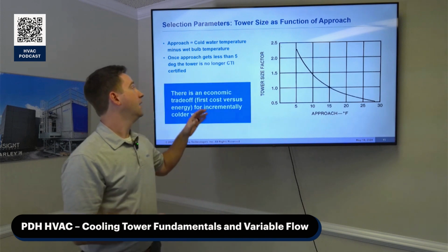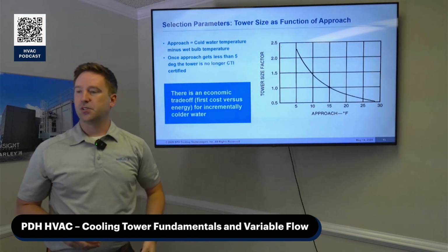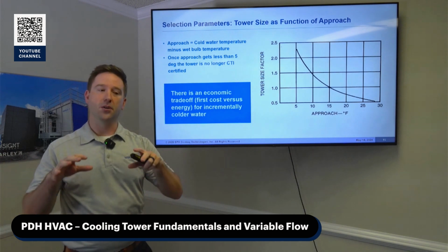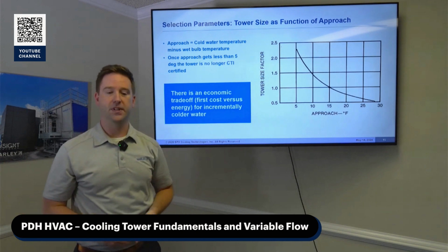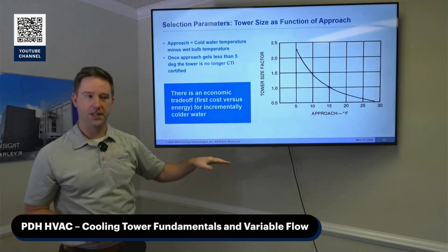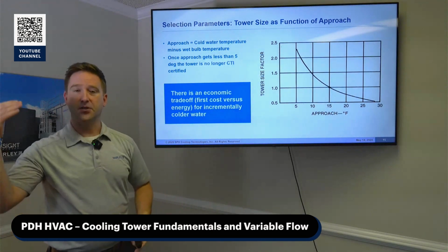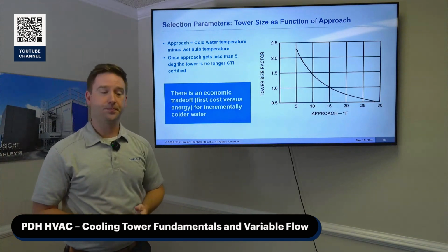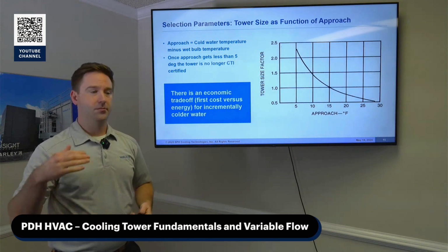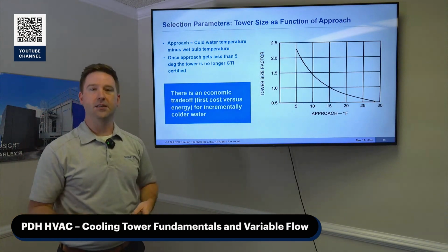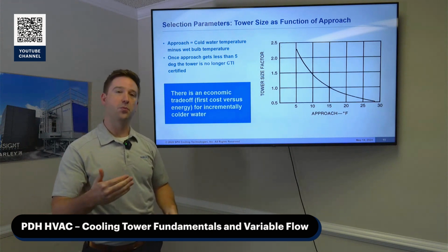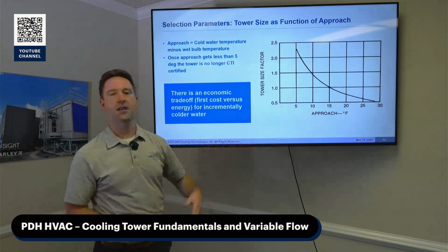I will make a note. CTI, they're the Cooling Tower Institute. They're the ones that come in and test all the manufacturers' cooling towers to make sure that they are performing thermally how they say that they are. They will not certify a tower below 5-degree approach. And that's just out in the world. It's really hard to be able to measure that specifically. Now, manufacturers, they know how their towers work. They can do studies and do tests and guarantee the performance of their towers, but it won't be CTI certified if it's less than a 5-degree approach.